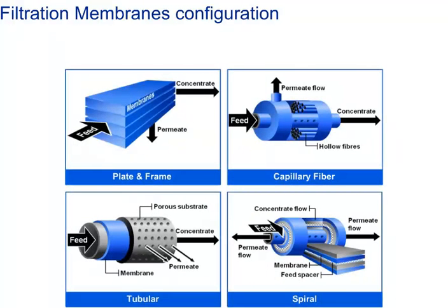Here are a few examples of commonly used filter membranes. The type used varies on application and customer preference. They include filtration, low-pressure membranes, MF/UF, for turbidity and pathogen removal. Organic removal, nanofiltration, NF, for NOM removal. Inland brackish desalination, RO or NF. Seawater desalination, RO or two-stage NF. Membrane bioreactor, MF, UF, MBR.